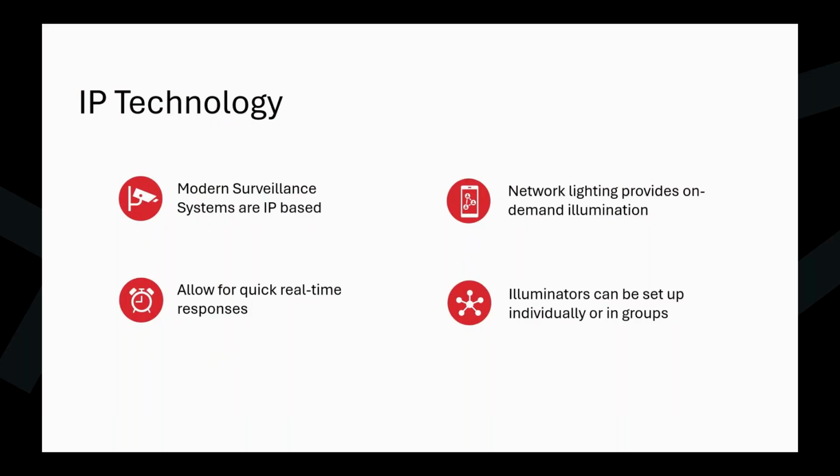Our previous case study that we looked at for Tennessee and Indiana, for example, they decided to go with the IP PoE products on the basis that they can log into them externally, they can play around with the power settings, and they can also check on the operational status of the lamps. They can do troubleshooting all from the comfort of their office. And so that is an important aspect to consider as well, whether that would be useful for your particular application.